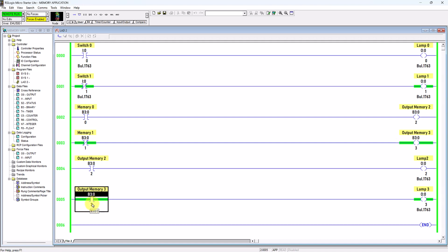How do we know it's closed? You can see the green highlight. The green highlight means the instruction is closed. Just like this one. The green highlight means the instruction is closed. This one also. So it can be the normally closed instruction remaining closed, or the normally open instruction triggered to close. As long as there's a green highlight, it means this instruction state is closed.